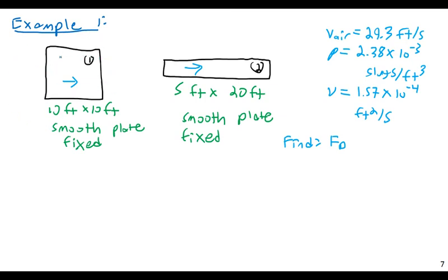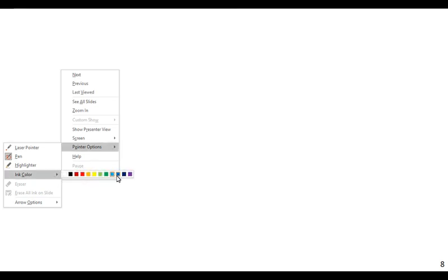So usually we think of drag in terms of projected cross-sectional area, but for plates, the flat surface generates the vast amount of the drag force. Everything else is really a rounding error. So let us calculate it first for plate 1 and then for plate 2.